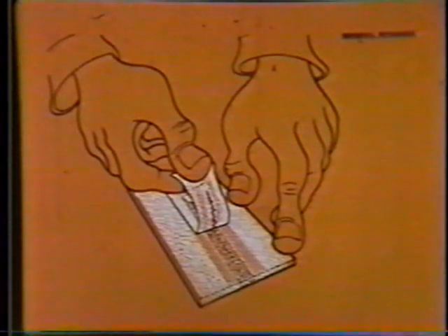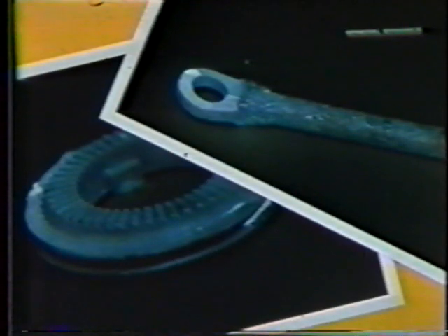Recording of penetrant indications is sometimes done using a strippable lacquer. Several layers of lacquer are applied over the indication and allowed to dry. The coating is then lifted, bringing the indication with it. Another method is to spray the indication with a fixer, and when dry, lift the indication with transparent tape. The tape is then transferred to the appropriate test document. Photographs are excellent in recording indications, both black and white and color, with Polaroid film providing the ultimate inconvenience.